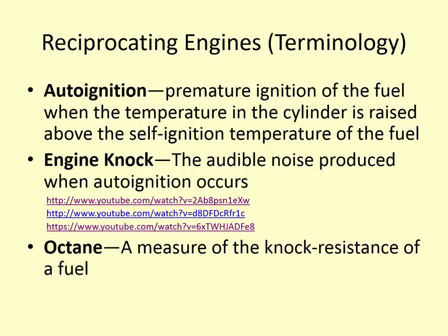So octane, or additives that increase the octane, is added to fuel, and the octane is just a measure of that knock resistance. So if you do have a vehicle that has a problem with knock, one possible solution is to increase the octane of the fuel that you use.